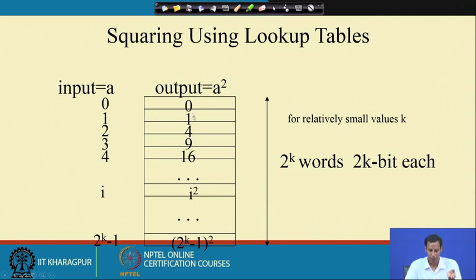So if I consider k number of bits for this, I need 2 to the power k positions, so the length of this ROM will be 2 to the power k, along with that each of the length of twice k bits. So if my k is more, in a wide range, at that time the corresponding ROM size will be very high. Very high means it will consume more area as well as more power.